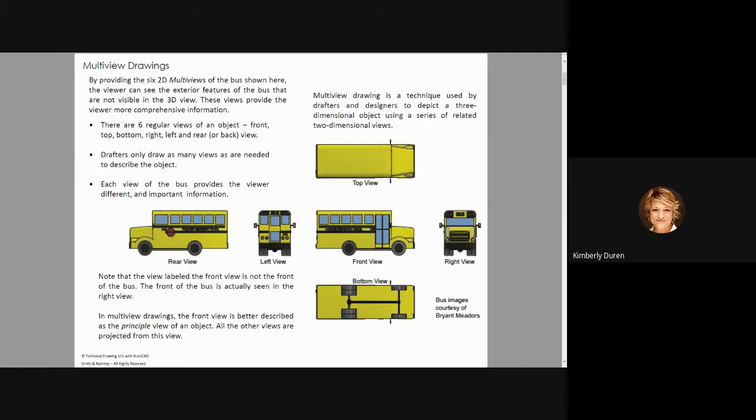So here's this wheel right here. It starts right there. It goes so deep and it stops right here. So I can actually project geometry if they are in horizontal and vertical alignment. And it's very important to do that because I don't want to remeasure this thing. I don't want to measure where this one is and then go back and have to remeasure this drawing. I want to simply line these up, and with a vertical rule, absolutely vertical from view to view, I can project that geometry down and draw this a lot quicker.